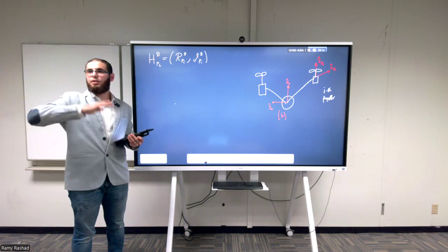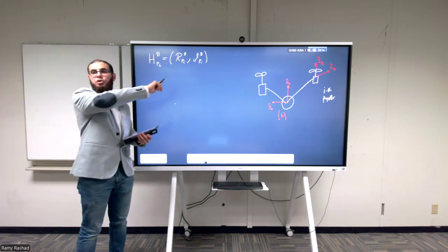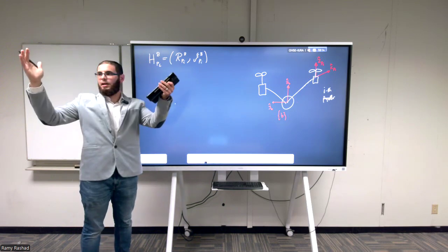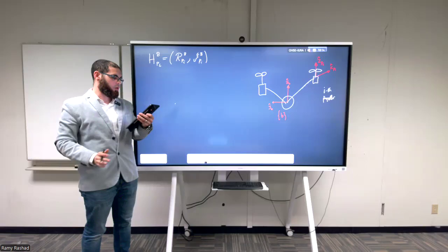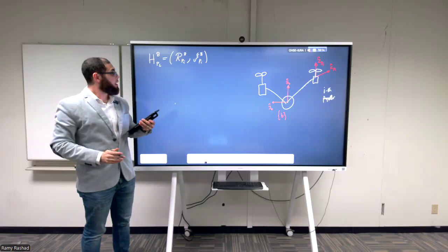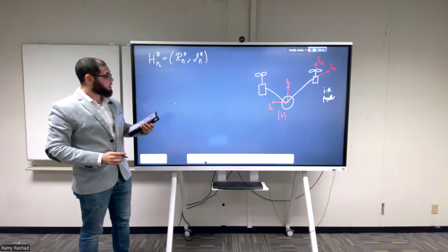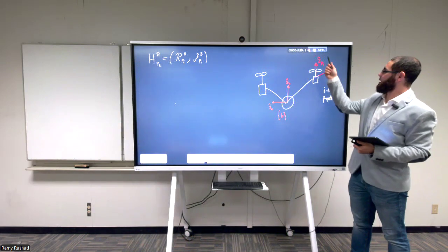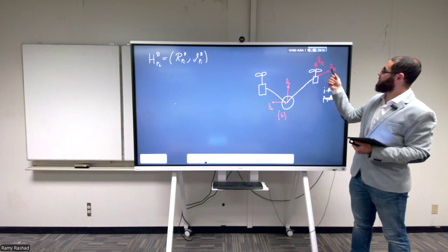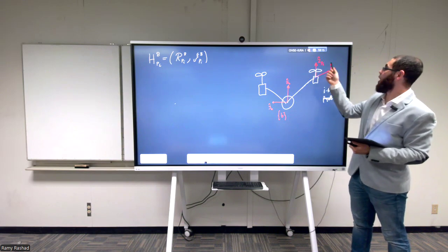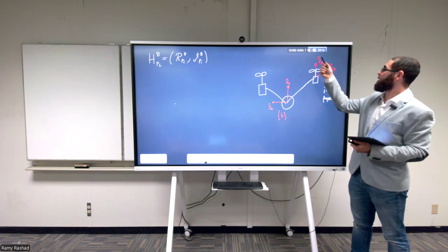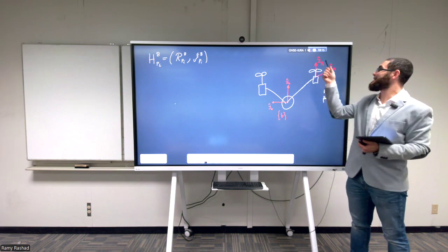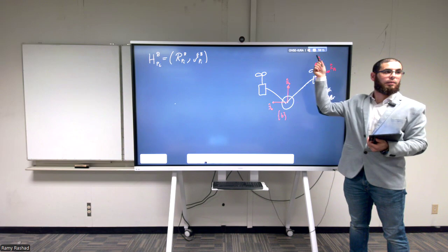How do you represent one frame with respect to the other? By homogeneous transformation. I write them like this, but you know that it can be written as a 4x4 matrix in the normal way. The interesting thing here is the rotation matrix, R_PI. If I look at this direction, this is very important, because this is the Z_PI hat.